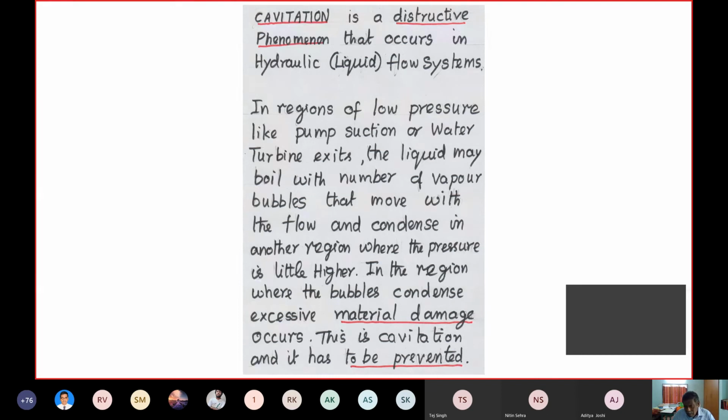And two things, people talk about the effects. Okay, or one is the efficiency comes down, or maybe three things I can say. One is the efficiency of the pump will come down. The first one is probably the material damage. Material damage means, see, when a pump is bought or the pump is put into application at some site, how many years you would like it to run without much maintenance?